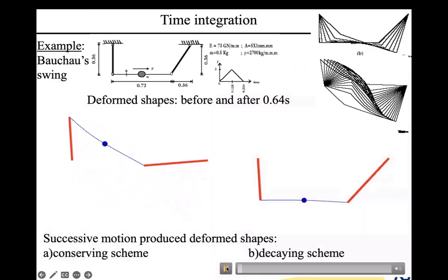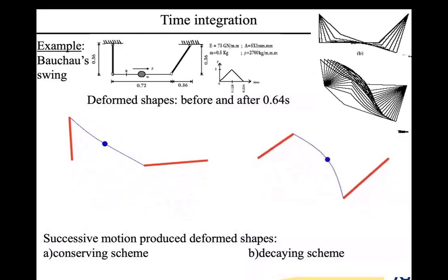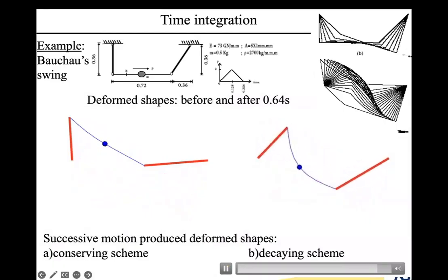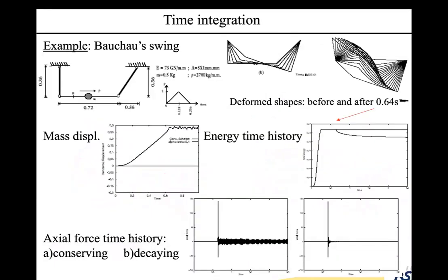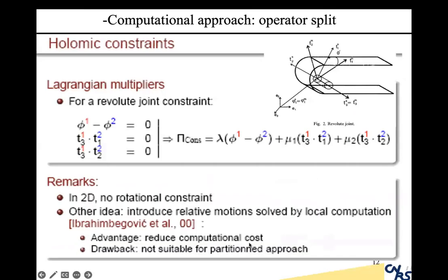If I have decaying to take out this high frequency, you see, poof, after it comes down, it keeps going without any difficulty. So that one really becomes more robust because you remove the troublemaker, the high frequency, and it is not there, so it cannot trouble your computation. You can turn as much as you want. There's no problem. This is the moment when this component wins at 0.64. If you have an energy conserving scheme, you're still going to be conserving energy. If you have this high frequency dissipation, you take out this energy, and your stress will have a better profile than the one governed by some kind of numerical noise that you do not fully control.